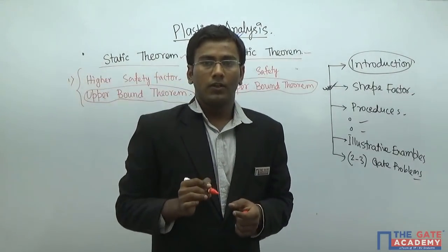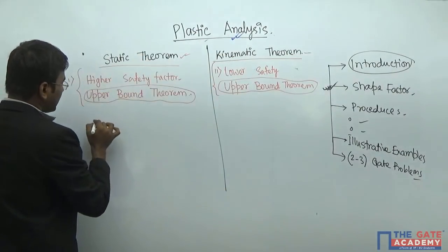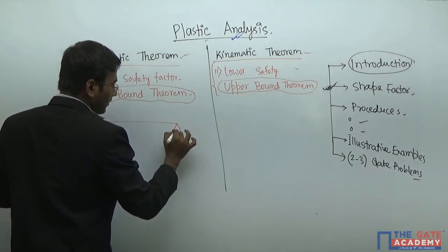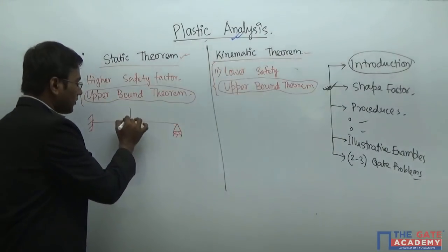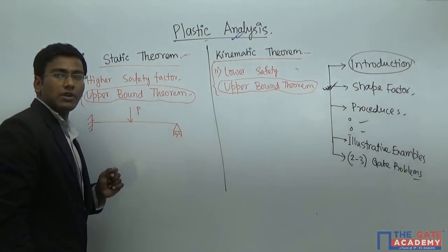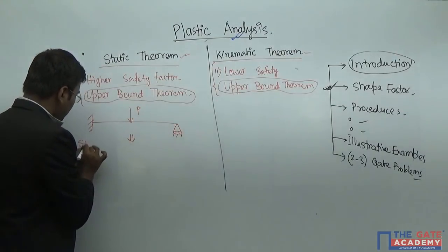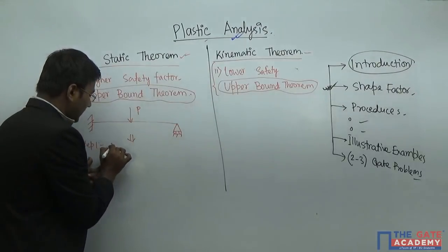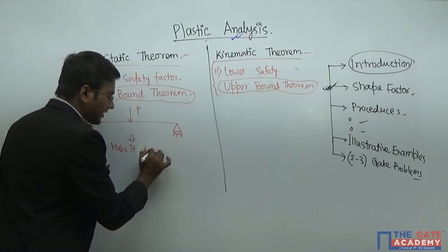Now, what is the design procedure for static theorem? Just imagine this is a propped cantilever. We have to find the collapse load here. Just imagine. First step is step 1. We have to make it a determinate structure.